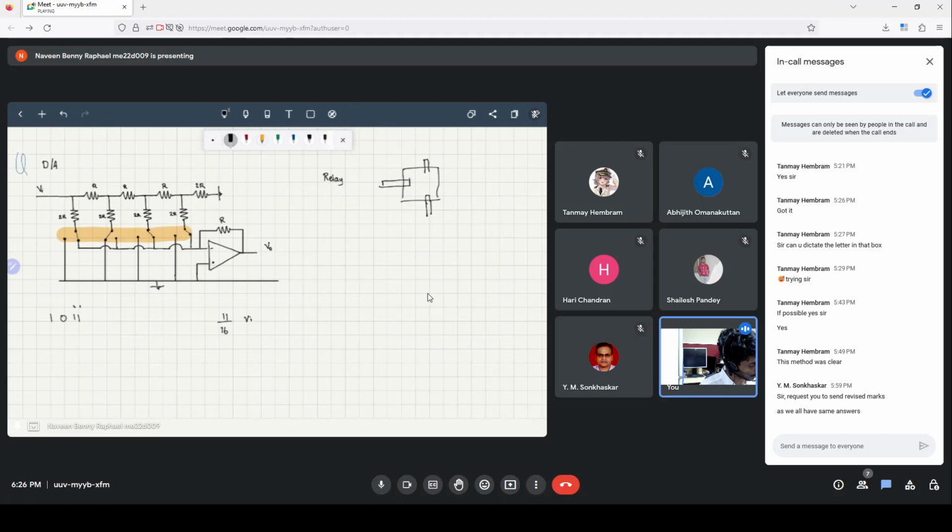Here there will be an electromagnet, and here we'll have a small piece of iron which is not connected to this. So when you provide current or voltage here, the electromagnet switches on, and therefore the switch closes. We discussed the NO and NC contacts earlier, and it's essentially like that. Because of the presence of this electromagnet, all we need is an input, so we are electrically actuating this.